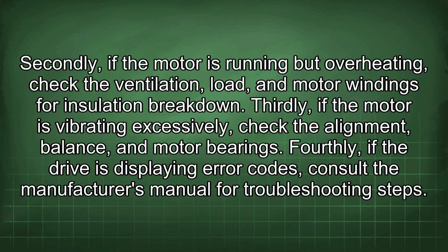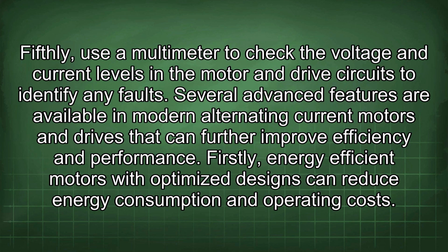Thirdly, if the motor is vibrating excessively, check the alignment, balance, and motor bearings. Fourthly, if the drive is displaying error codes, consult the manufacturer's manual for troubleshooting steps. Fifthly, use a multimeter to check the voltage and current levels in the motor and drive circuits to identify any faults.